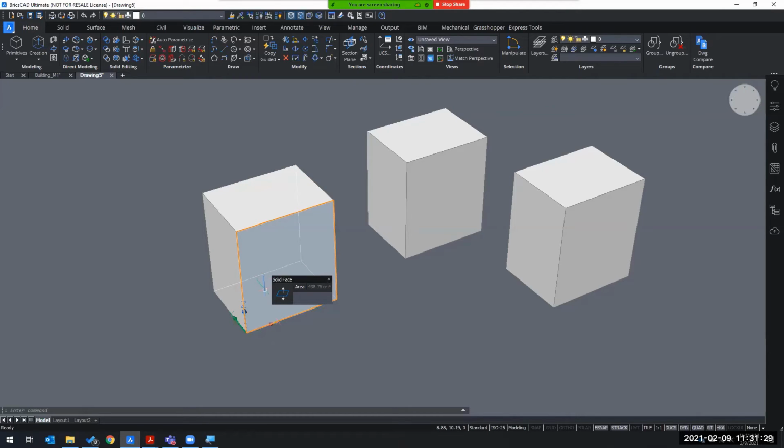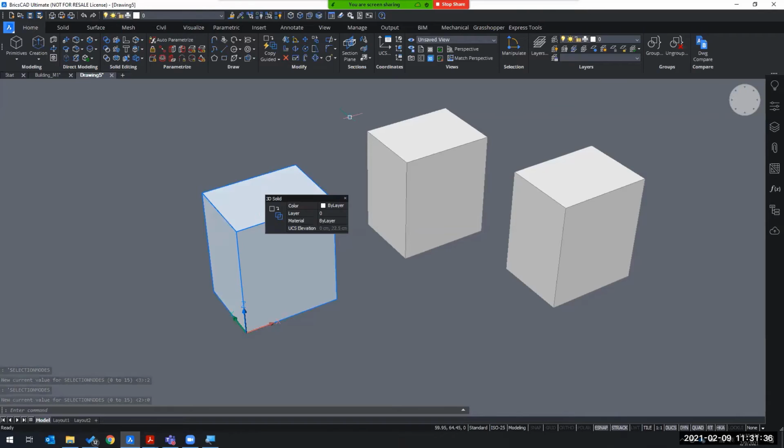And you can, of course, change your selection mode to 0, so now you have access to the solid. But depending on which phase of your model you're in, if you edit it in phases, you might want to leave this combination on. And if at some point you want to select the entire solid, you press the control key, and now when I hover, it's blue.